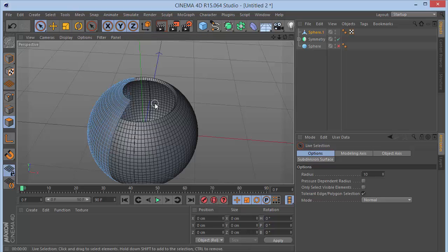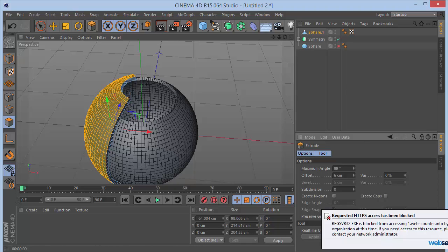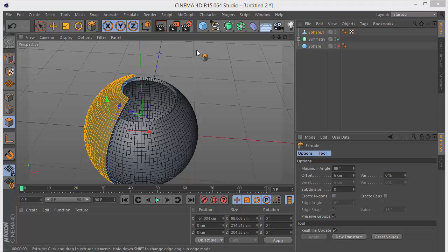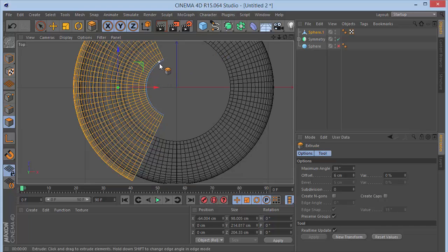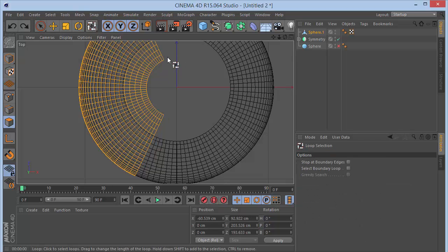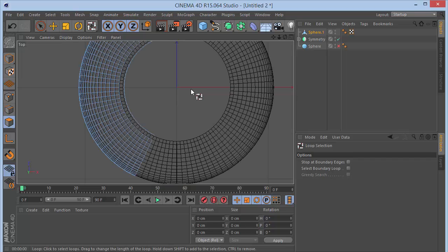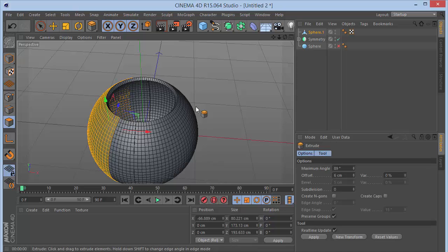And now I'm going to press Control A, press D on the keyboard and give it an extrude of 6 again. You know what, let's actually delete some more polygons. So let's go back, and let's Control Z to remove the extrude, and press UL, and this one, and this one, this one, and this one, hit delete. I'm going to select the bottom ones and hit delete again. Now let's select this once again, delete, and select this one, delete, and now we can press Control A and D and set an offset to 6.